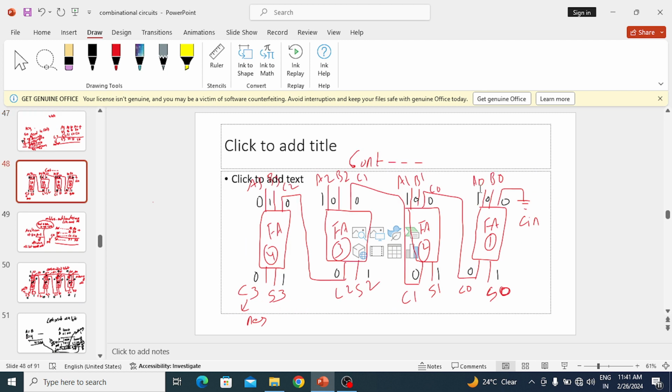See here in the circuit, suppose I observe a0 and b0 are the same, 0 0 or 1 1. Same means 0 gives me 0, same 1 gives me 1. So I need not wait until it provides the carry. Based on this only I can know this value. If both are zeros, it will be 0, both are ones, it will be 1. When both are different, we cannot know based on this. Based on the first carry only we can know further carries. But anyhow we are able to know the carry values without waiting.